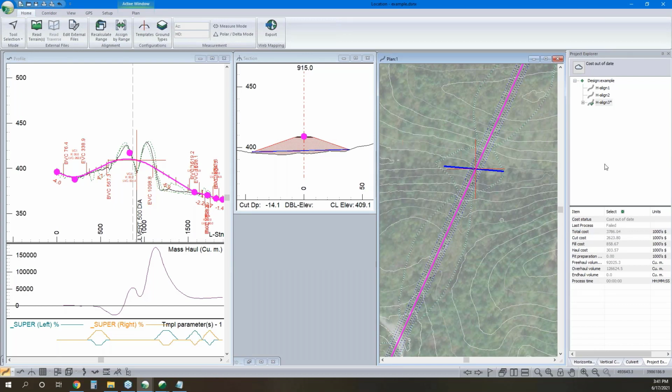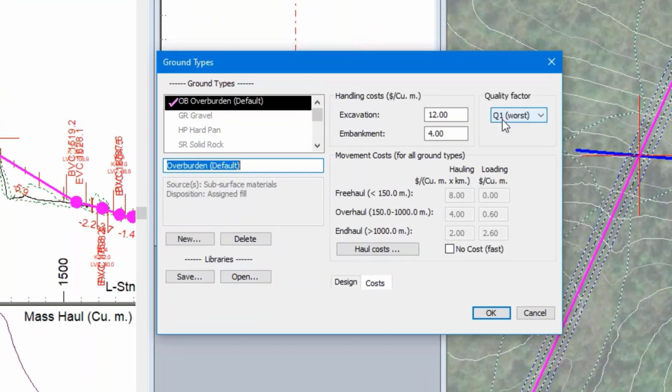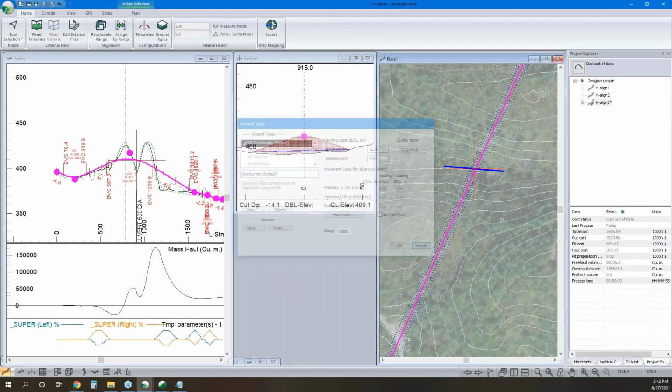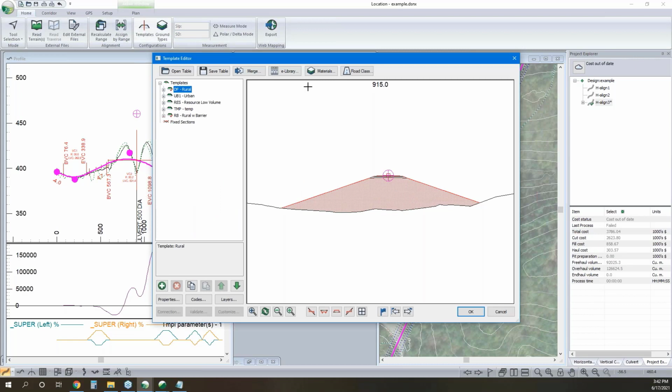Now, to add a little more complexity, and I'm not going to go into much depth on it, we can also add quality parameters. If you need a high quality material, the software is going to look at what you have assigned for quality parameters, and the solver is not going to actually use the mass haul diagram. It's going to use our opti haul diagram, which accounts for balancing your individual materials by individual material with the specific material expansion and compaction factor, and gives you a really smart estimate on what's going on here.